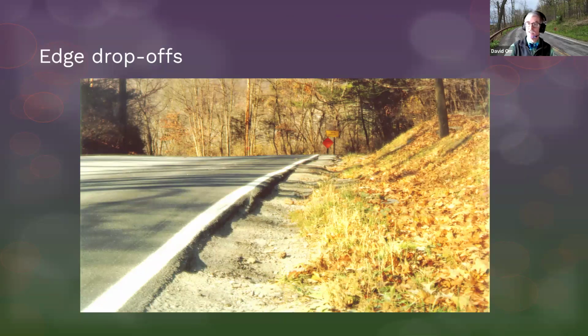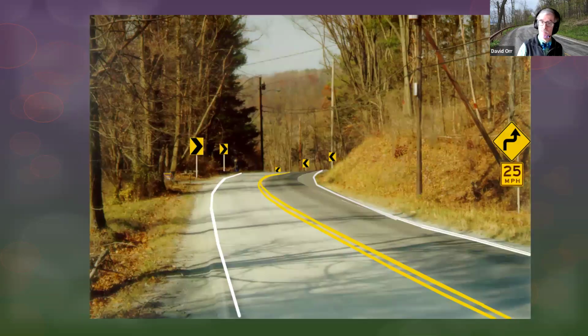So that's why some of you mentioned the safety edge or a rumble strip, or widen that out a little bit and make it slightly wider on the inside and then restripe it when you're done. And you've improved safety for almost everybody. Okay? And again, you can even change the chevron height a little bit, by the way, to help people around the corner. Again, remember, standards are minimums.